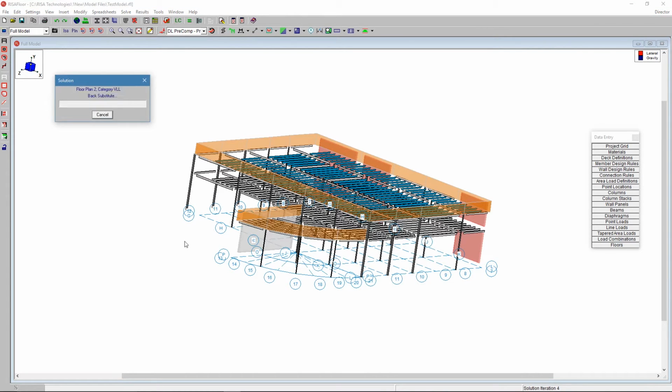It's going to be calculating all the loads down the structure. If you have a wall panel here, we're going to be accounting for that upper portion of that wall panel, calculating the loads down the structure. You'll notice here I have all sorts of different types of members going on, so there's lots of loads being designed. I use the load combinations for LRFD as well as ASD because I'm doing a collection of different things in this model. So it will calculate all these forces.